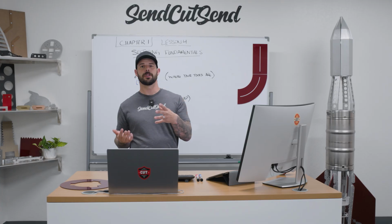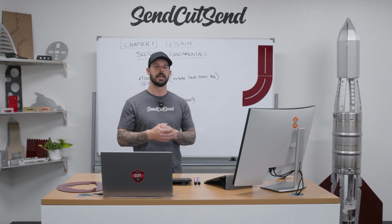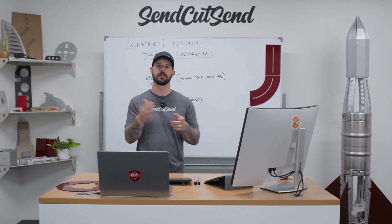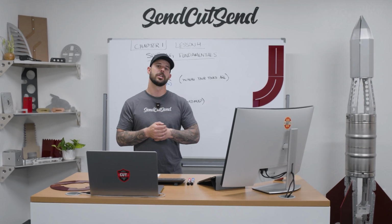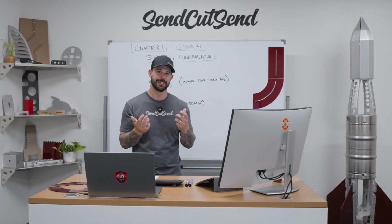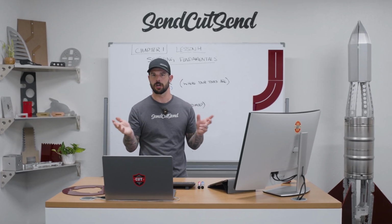Now, the big reason that I like to use this timeline is not apparent yet. It's going to make a lot more sense as we build out a lot of features and sketches and have more complex parts. We're going to use this to edit our parts and change things and features in the background. It's also a great way that if your part does break, say you didn't create a sketch correctly or you made a reference to something that no longer exists, then you can use this history, this timeline, this roadmap to go back and correct those little things without just starting all the way from scratch.